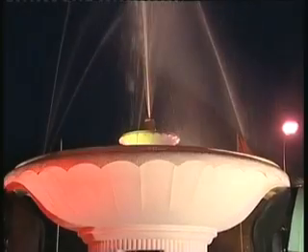So we have talked about attached growth systems which are commonly used in wastewater treatment processes. One is the trickling filter, and in trickling filter itself we can go for high rate trickling filters and standard rate trickling filters, and for RBC we have seen how to design it, and nowadays activated RBCs are being used. It is a combination of rotating biological filters as well as the activated sludge process. Next class we will discuss the anaerobic process.